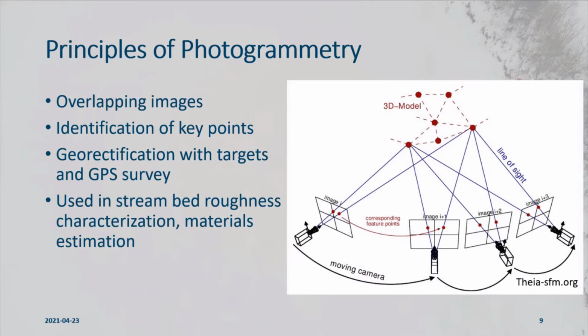But coupling the power of drones with the algorithm of photogrammetry, it's possible to get a pretty detailed 3D surface model of something like an ice cover. Photogrammetry uses changes in perspective and common points across multiple photos to establish distance between the camera and the points of interest. This algorithm works in a similar way to how your eyes perceive distance through parallax error. And as long as the points that you want to capture are found in at least 2 images, the algorithm can use them and reproduce them. In this research, we used Agisoft PhotoScan Professional, which automates a lot of the process for us, which is really nice.